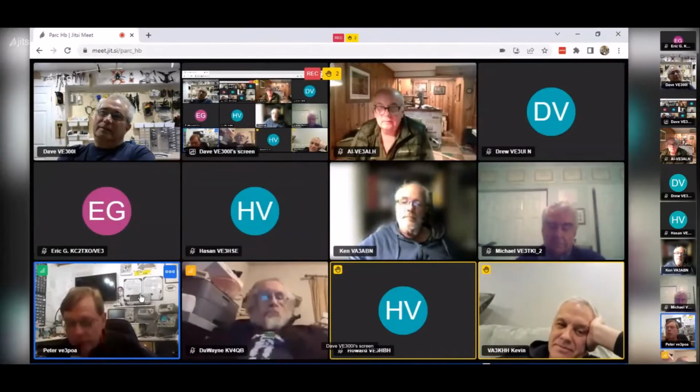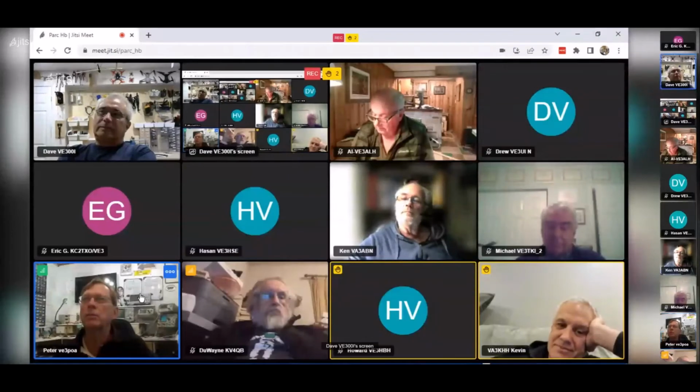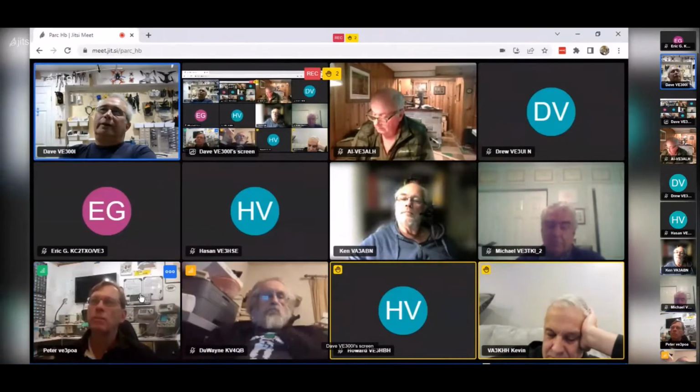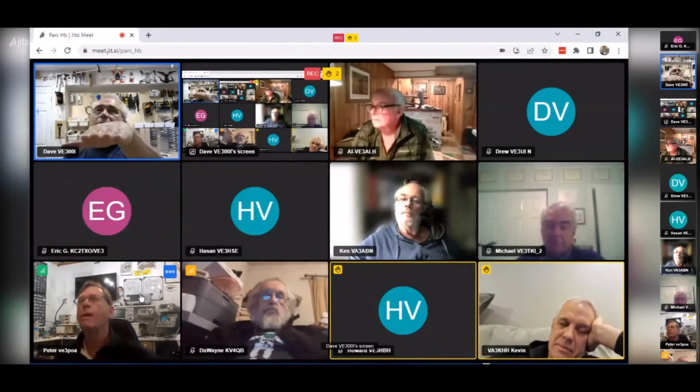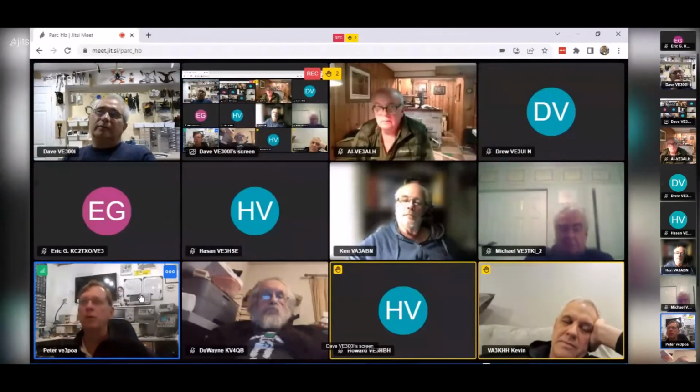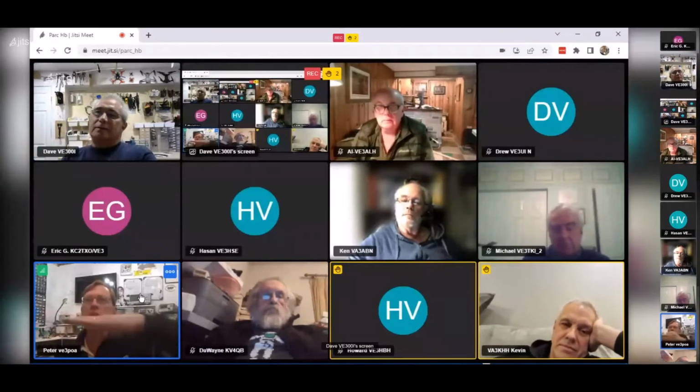Dave, mounting the sensor boards, does the orientation of mounting them matter? Can you mount them in the position you want and then calibrate from that position? No, you can't, because then you have to go through that whole trig math and figure out what the angle is. If you change the orientation, just by flipping the board upside down, the way you measure the pitch is completely different. No, I realize that. I mean, when you're designing it, do you have to design with the board in this kind of plane, or it doesn't matter? Yeah, you have to.